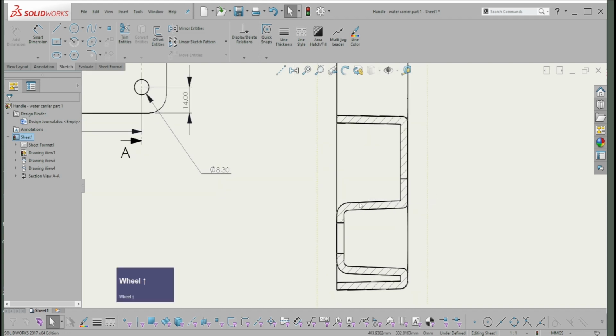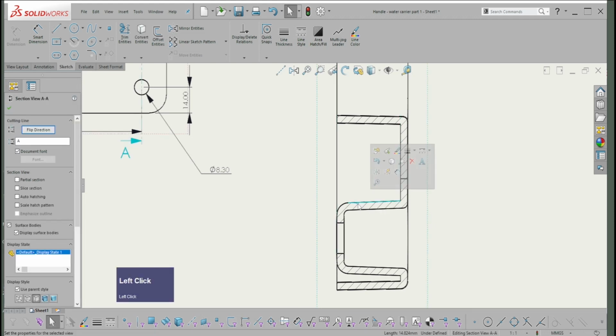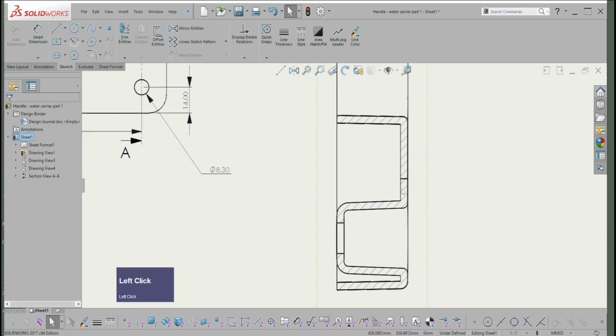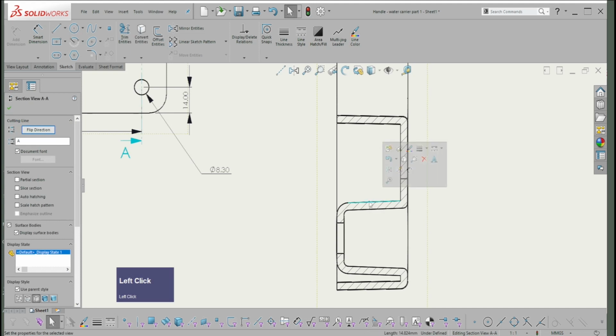Just to show you, to put in the virtual sharp, I hold the shift button down, or I can just click on the line first. Okay, so there's a little mistake that I might have made. Be careful not to select the view and a line, and just to select a line, otherwise you might get an error. So I've selected a line, holding the shift button down, selected another line, and then put in the point.